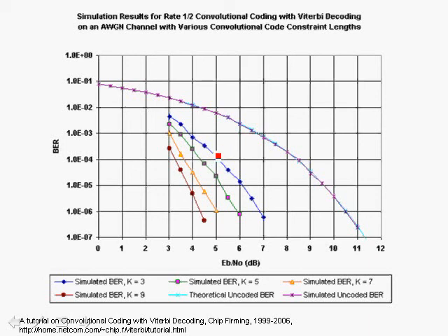All right. So what if we use forward error correction coding, and how does that improve our performance? In this case, we use a constraint length k equals 3, which is what we've been discussing. So you have m equals 2 as the size of the shift register, 2 memory elements. And you get a dramatic improvement in the bit error rate performance versus no forward error correction. If you look here, for example, at an error rate of 10 to the -5, we're seeing about a 3.5 dB improvement over not using forward error correction.